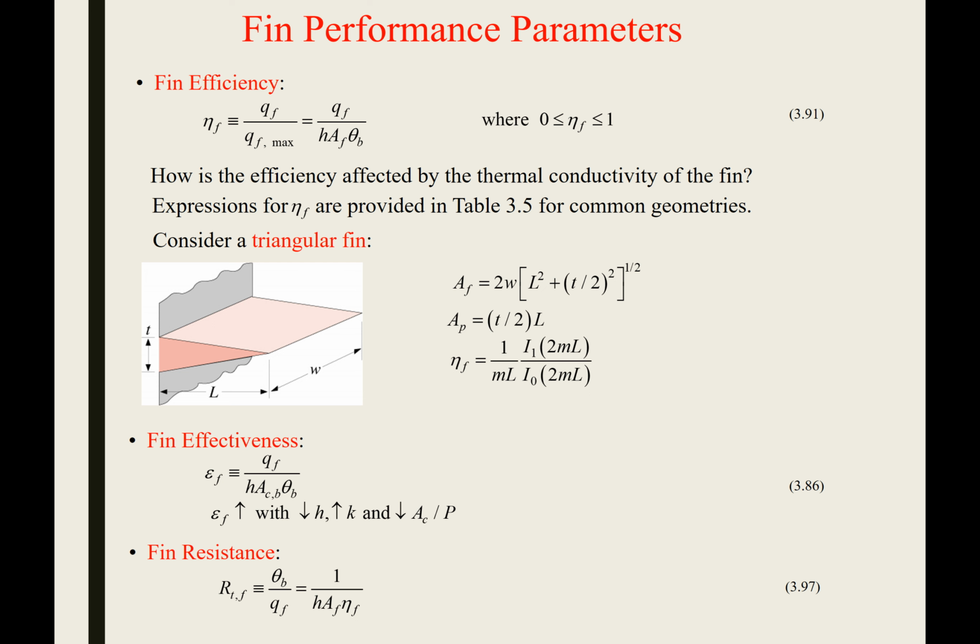So we've added these fins to some big solid because we want to increase heat transfer. But because those fins are long and we see their temperature decay the longer they get, they're not perfectly efficient, especially if you consider a really long fin. At this left end it's going to get really hot.